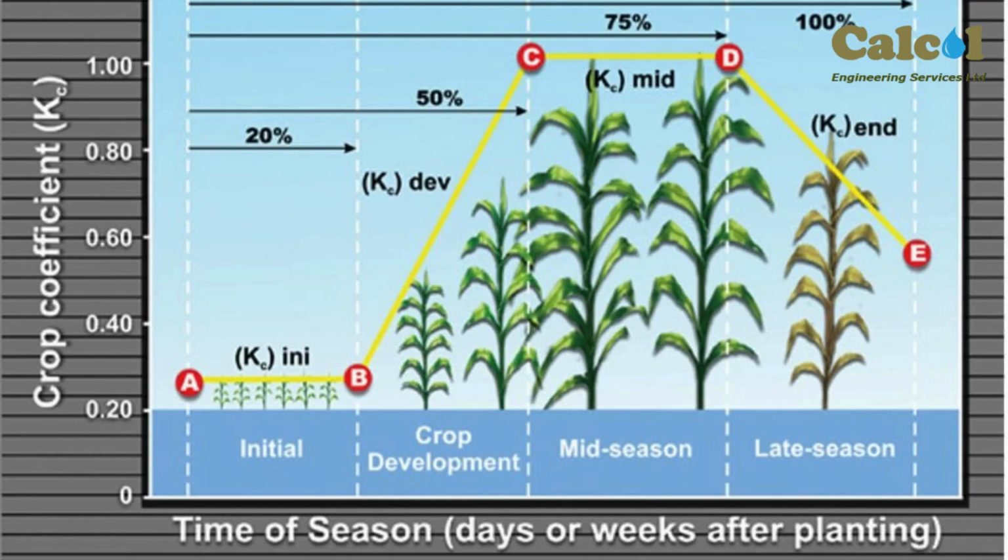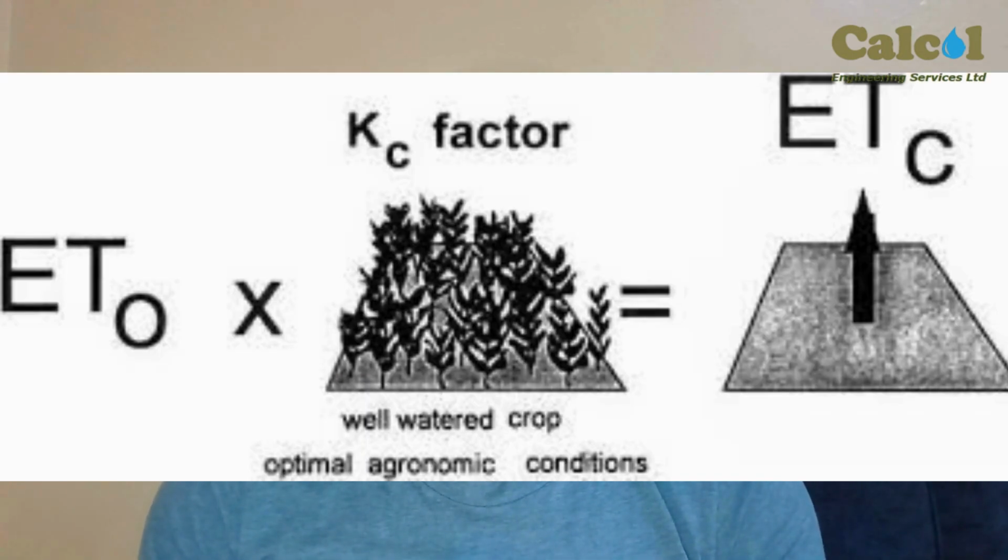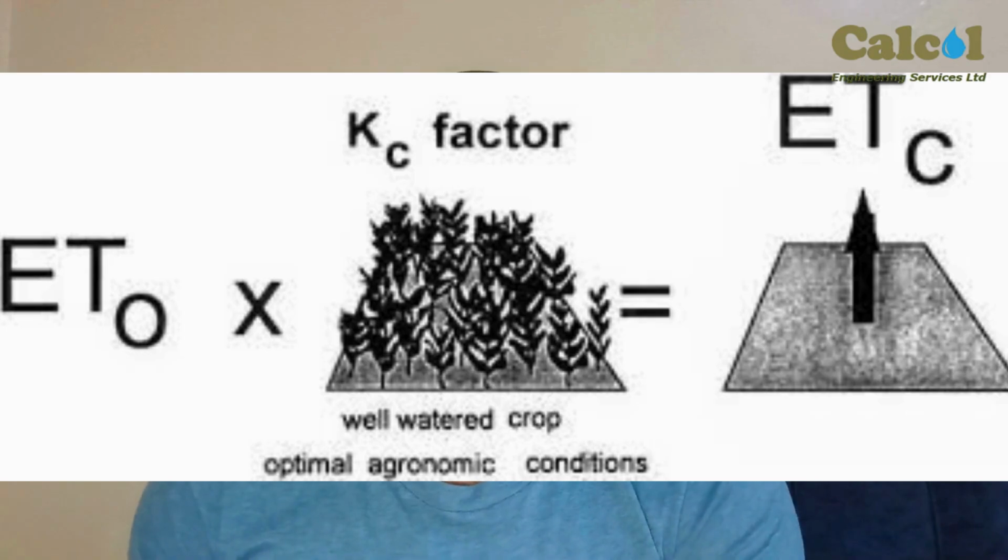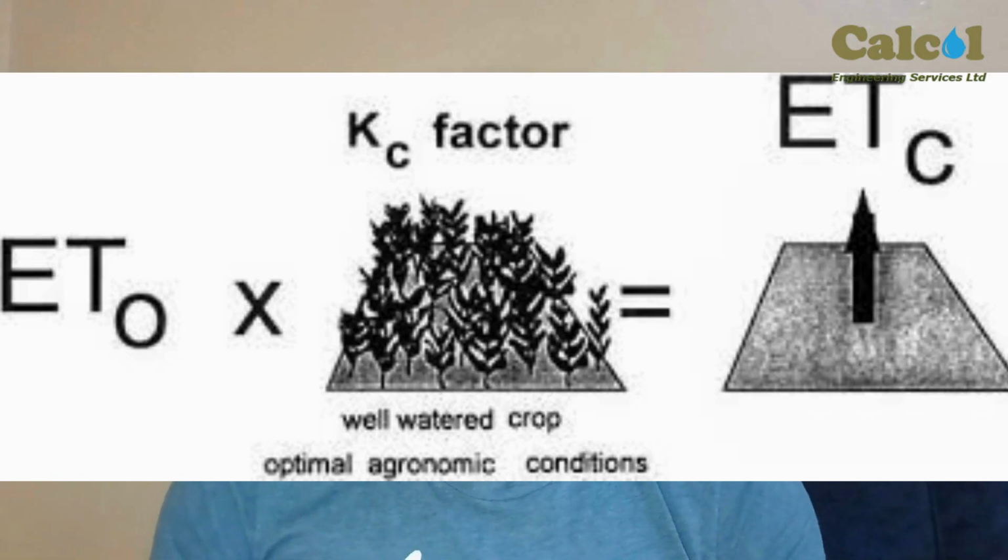When calculating the ETc, which is the crop water requirement, you must determine the growth stage of the crop and their duration, then select the appropriate Kc values to apply as per the formula attached. In the formula you can see that ETc is given by Kc times ETo, where ETo is the reference rate, and Kc is the crop factor, which is determined by the growth stage of the crop, the type of the crop, and also the climatic factors that come into play.